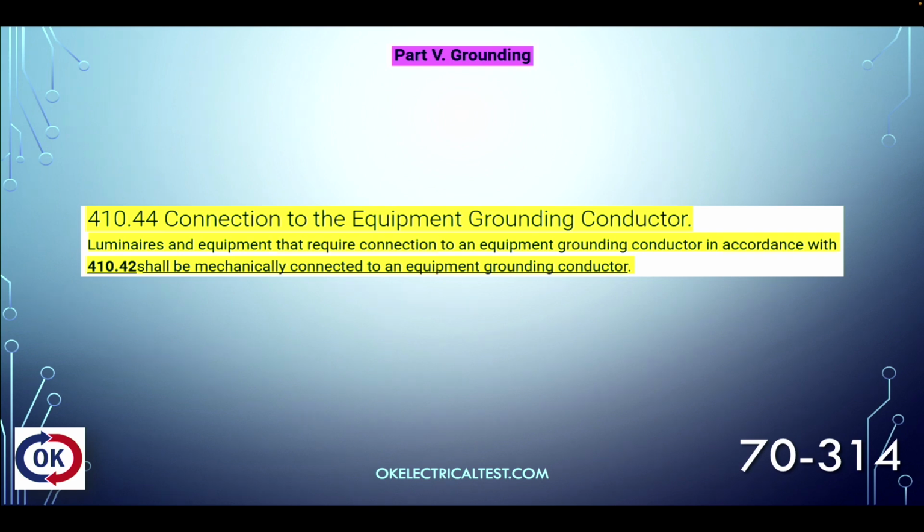410.44, around page 314, we've got 410.44, connection to the equipment grounding conductor. Luminaires and equipment that require connection to an equipment grounding conductor in accordance with 410.42 shall be mechanically connected to an equipment grounding conductor. So we need to connect that mechanically to an equipment grounding conductor.